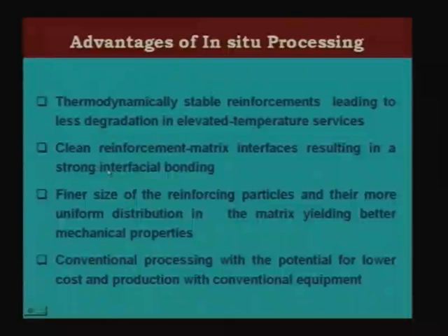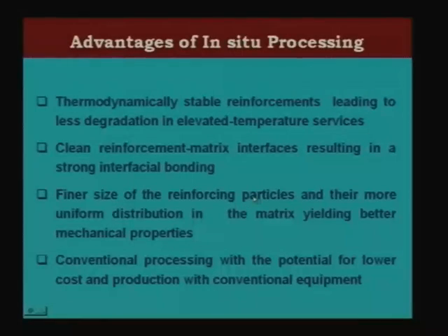In addition, the reinforcement matrix interface is very clean, and because of which you have a strong interfacial bonding. You have a strong bonding because of the clean interface, because there is no reaction products formation in these cases, because the particles are themselves coming from the liquid metal. As a result, there is no reaction between the particle and the matrix itself. So, as a result you have a clean interface, and one can control the fineness of the reinforcement particles by